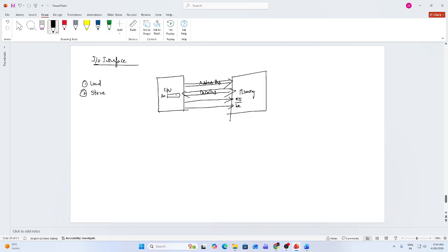The data present in the accumulator is kept in the data bus, the address to which it is sent is kept in the address bus, and the write signal is activated, so that the memory controller will read this data and write it in this address. These are the two instructions used to perform memory operations.